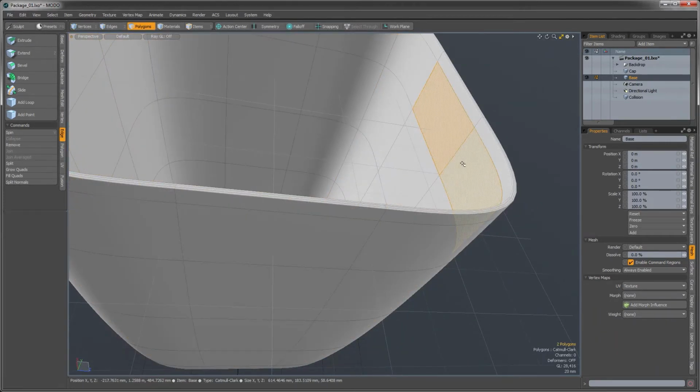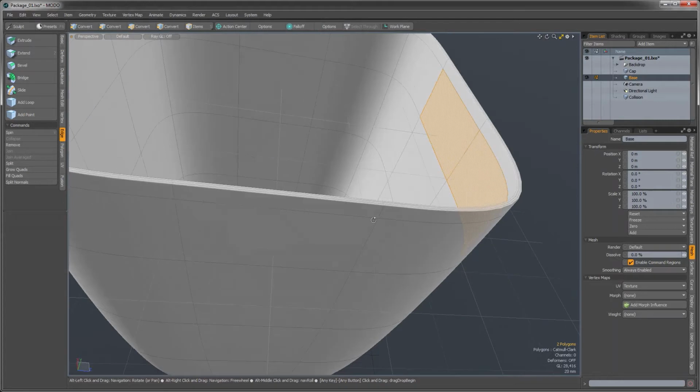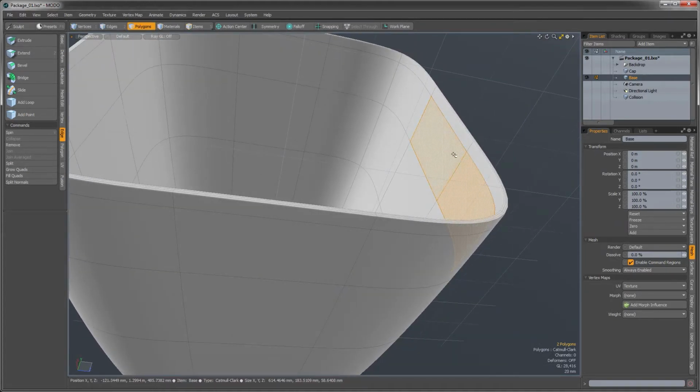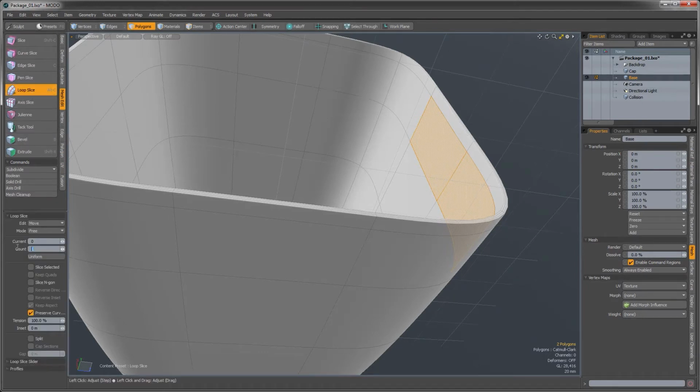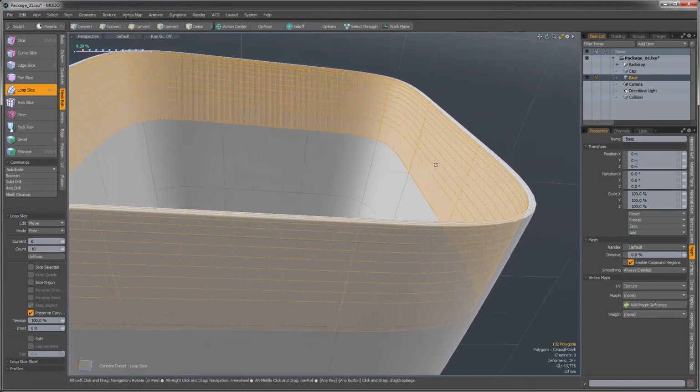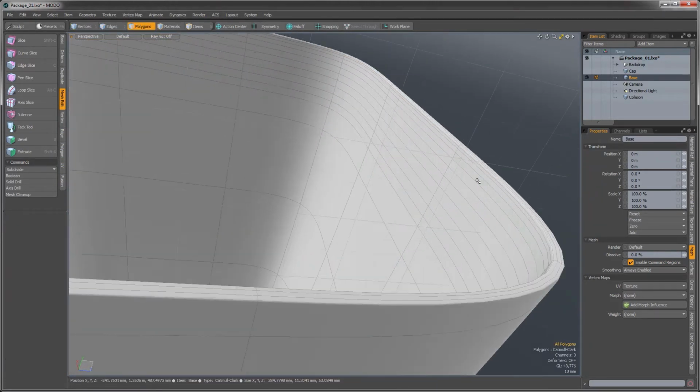Now, when the top and the bottom snap together, you kind of get these little grooves inside that help hold them together. It just uses pressure to sort of hold together since the two materials are somewhat flexible. So we're going to mimic that little lip that's on the inside. So I'm just going to quickly do my loop slice here again. And for this one, I'm going to give it a count of 10. And we're just going to make those uniform. And I think I'm just going to come down a little bit here. Maybe that one, then skip 2 of them, and that one.